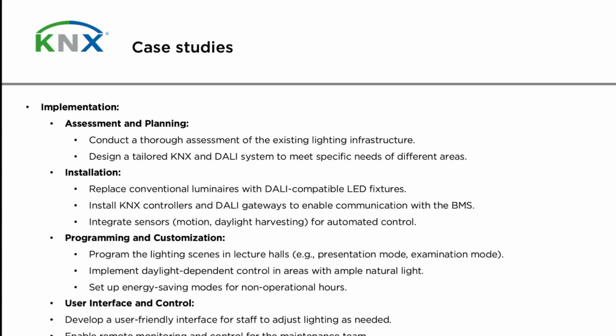We need to replace the conventional luminaires, remember, this is a retrofit, with DALI compatible LED fixtures or drivers, DALI compatible LED ECGs. We don't need to replace the lighting fixtures if we don't want to.